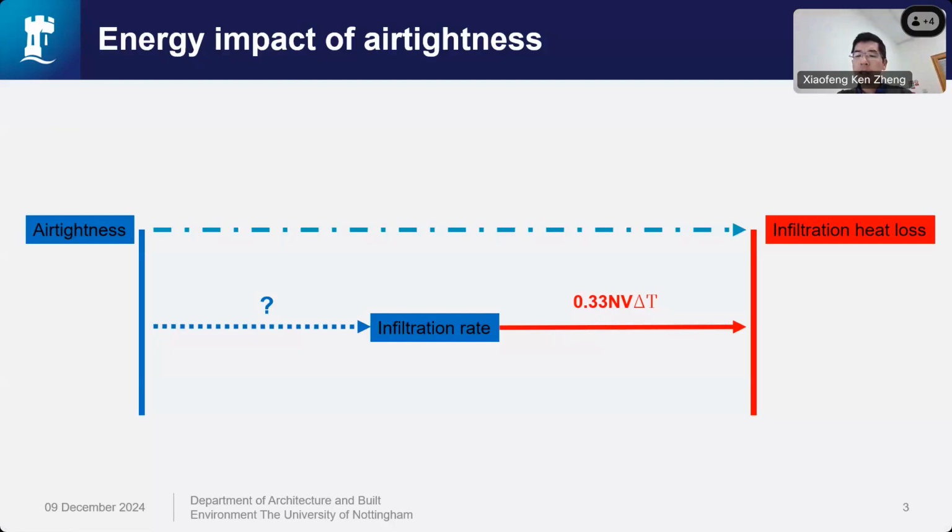So airtightness plays a crucial role in building performance, particularly in determining the energy required for heating and cooling. Measuring airtightness provides an essential starting point for evaluating infiltration heat loss. Infiltration can account for up to 1/3 of the building's heating load, with some studies reporting even higher figures. Once infiltration is known, it is straightforward to calculate its heat loss. Since direct infiltration measurements are often intrusive, expensive, and time-consuming to implement, airtightness is typically measured instead.